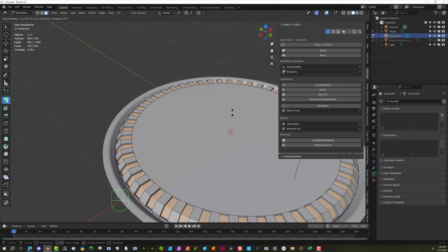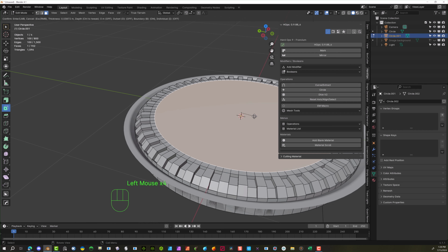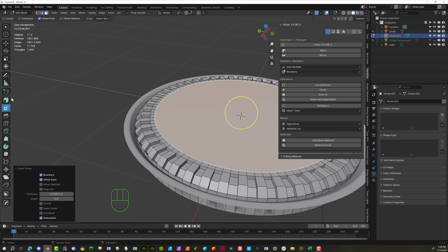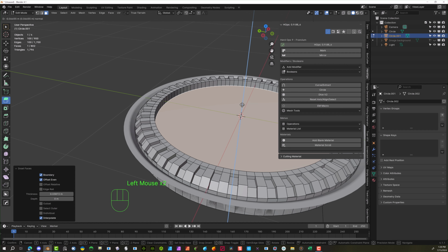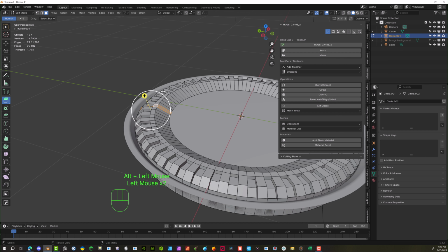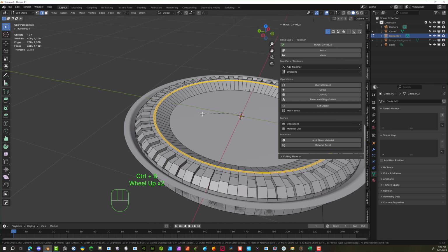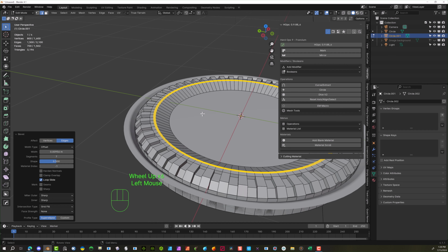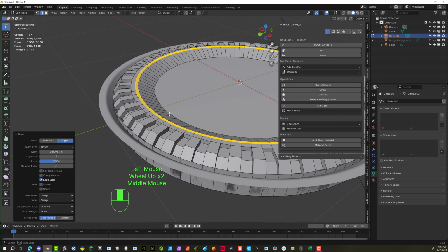And next we're actually going to a certain point here, and then we're going to go ahead and select another area. Now I'm going to actually hit the inset on the top here, bring that back in a little bit more. Again, we're going to hit this actually extrude and bring this down. I'm going to hit the S key twice to scale that section in. And again, we're going to select with the line tool and hold the Alt key again, select this edge here. And we'll hit the Control B again, and we'll pull this out and add a little bit more detail along this edge here. A nice bevel.